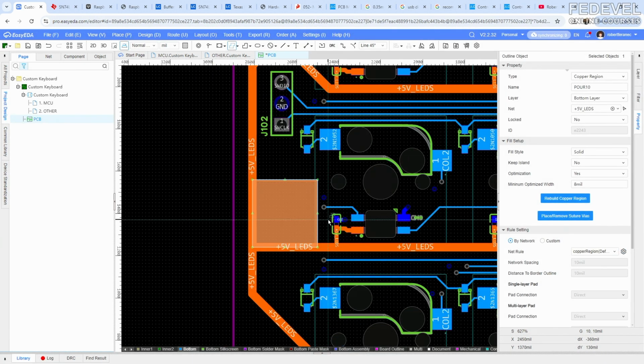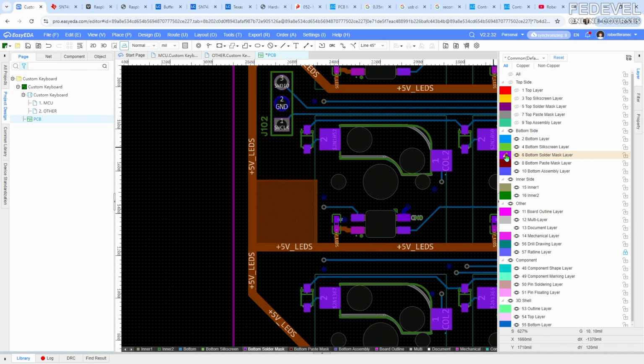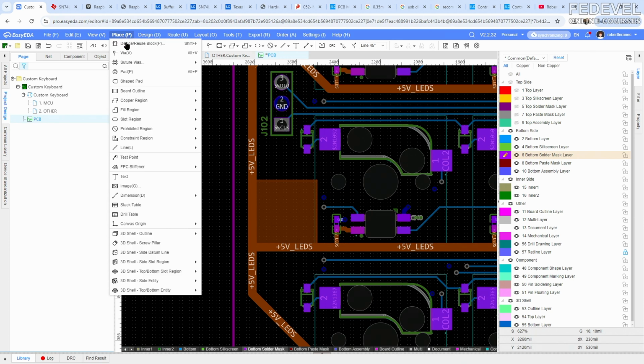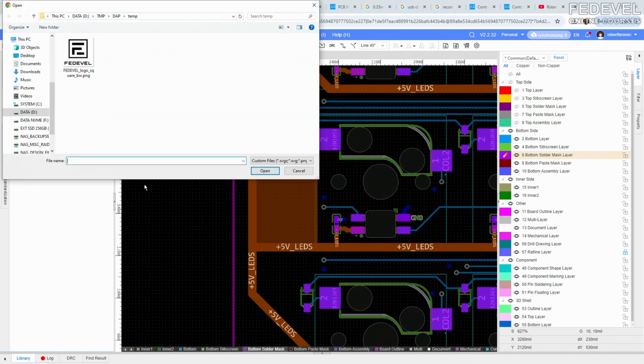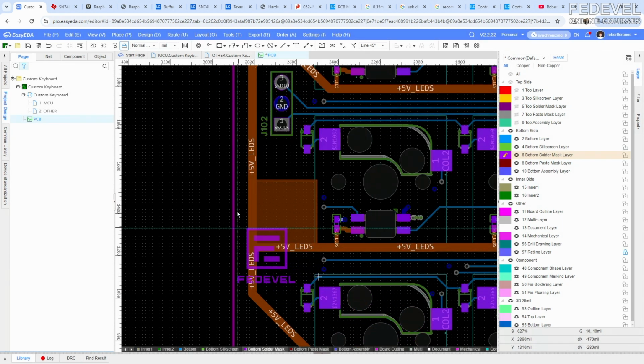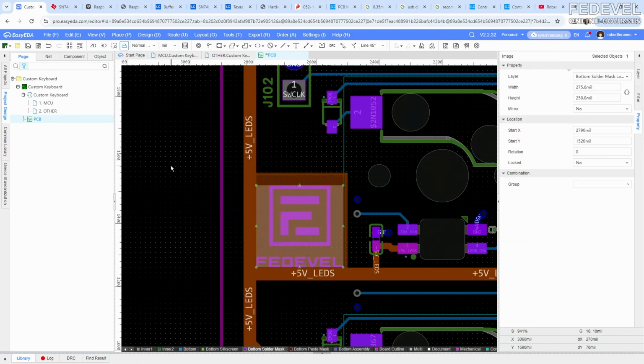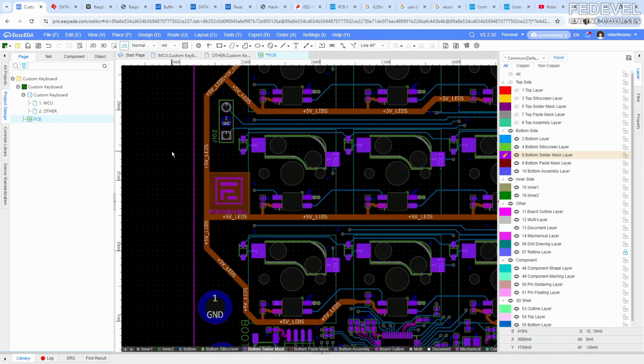And instead of placing the logo on silkscreen layer, we will place it on this mask layer. So we will unmask the area where the logo is. And when we do the gold finishing, be sure you use correct size and then click here, very important. So it will adjust also the other size. And when we do it this way, the logo will be gold, okay?